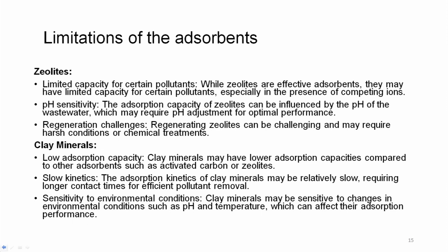Limitation of zeolite. Limited capacity for certain pollutants. While zeolites are effective adsorbents, they may have limited capacity for certain pollutants, especially in the presence of competing ions. pH sensitivity. The adsorption capacity of zeolite can be influenced by the pH of the wastewater, which may require pH adjustment for optimal performance. Regeneration challenges. Regenerating zeolite can be challenging and may require harsh conditions or chemical treatments.